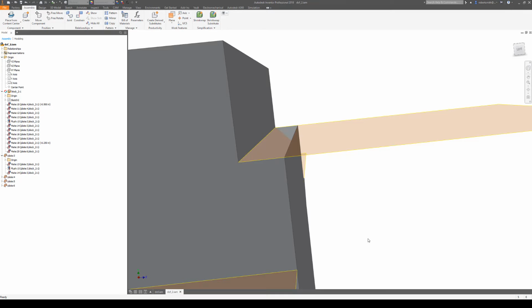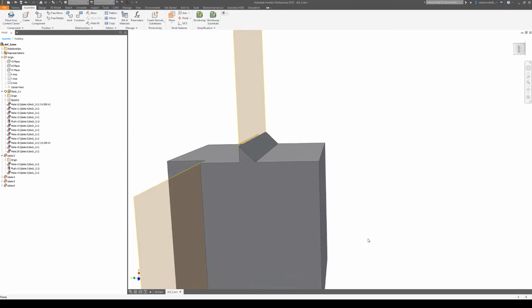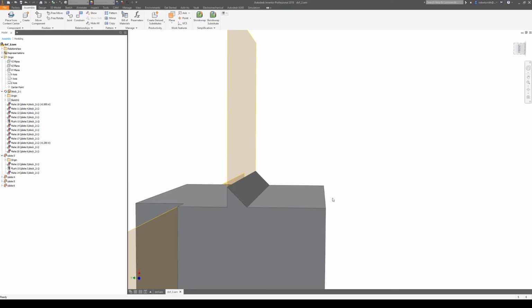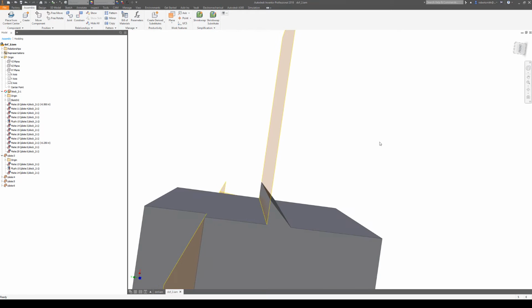We're often simplifying structures and changing them a little bit to make them behave better as analytical models, understanding that the results in that area, say where these two things meet, may not be as realistic as they were before, but overall the displacements of the structure, the stresses in the plate structure, for example, and the deflection at the end would still be good. I've seen cases like this where maybe it was a weldment where the plate structure and the solid were going to be joined together with a weld bead.